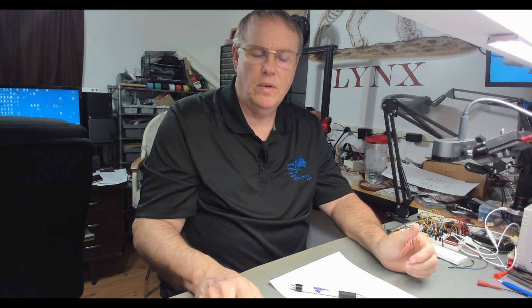It's sort of like trying to measure voltage. If you put your positive probe on something, but you don't have anywhere to put your negative probe, you don't have a reference. You can't really measure. You don't know what's high, you don't know what's low because you don't know what the reference for that is. And in the digital world, that's very important. So when we talk about a 0 or 1, it's not the same for every component. It's not the same for every circuit.